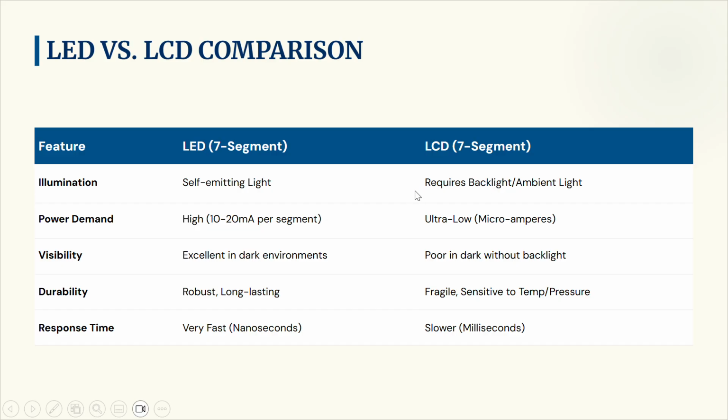So in electroluminescence, in LEDs, we have semiconductor material. You can think of a PN junction, that an LED has a positive p-type layer and a negative n-type layer. And we know electron recombination. When electricity runs through this semiconductor PN junction, electrons from the negative side jump across the junction to fill holes on the positive side, and then photons are emitted. Because electrons will be dropping from a higher energy state to a lower energy state, they will release their energy in the form of photons.